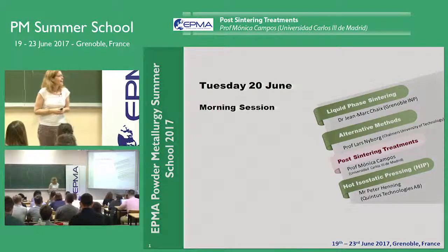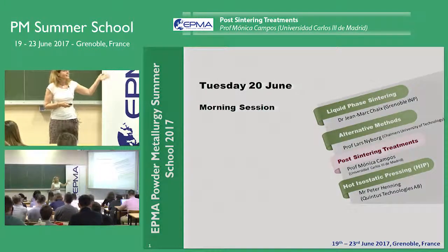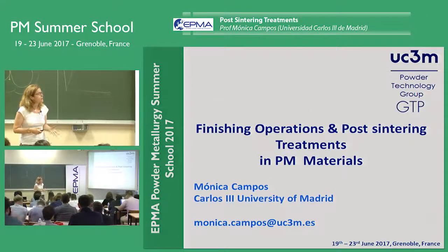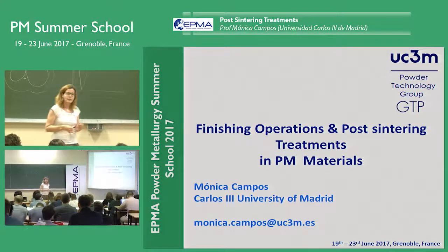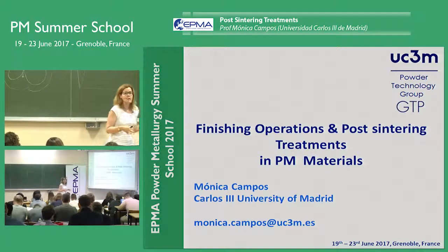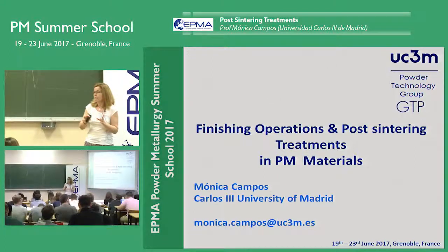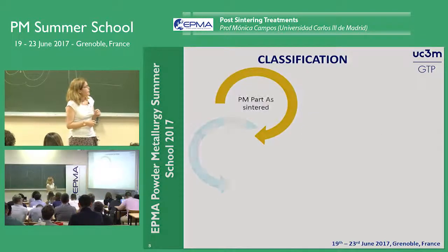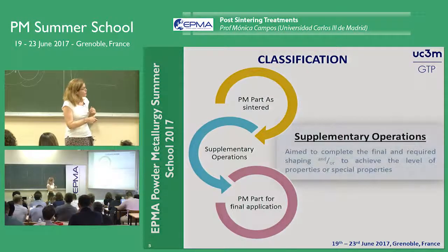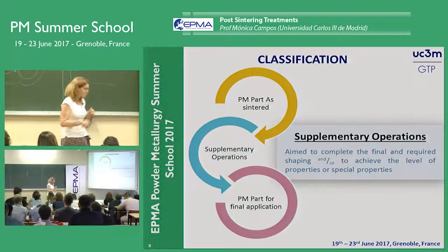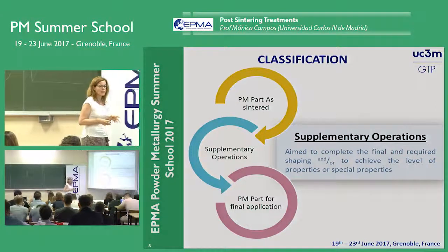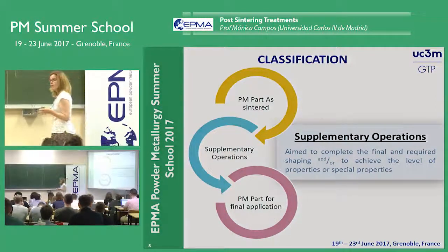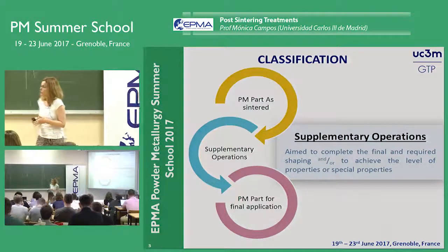Okay. And today my talk is related with post-sintering treatment. Post-sintering treatment is a big group of finishing operations that we can apply when we need to change something from our PM component in the as-sintered state. When we have the final component after the furnace, maybe we want to modify the shape, we need to adjust the geometry, or we need to change the microstructure.